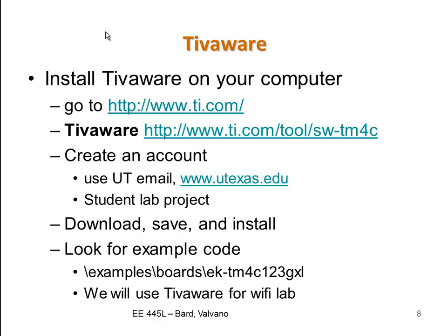So everything we do in this class will be register level I/O programming. There will be a register and there will be a number, and you're going to put that number into the register, and you're going to read the data sheet, and you're going to know why you put that number in the register. Nevertheless, once you graduate from the great University of Texas and go get a job and you're working for real, you will then use the peripheral driver libraries of that processor, and you will ask, may I please have a 1,000 hertz interrupt? I don't care how you do it, I just want it to be 1,000 hertz.